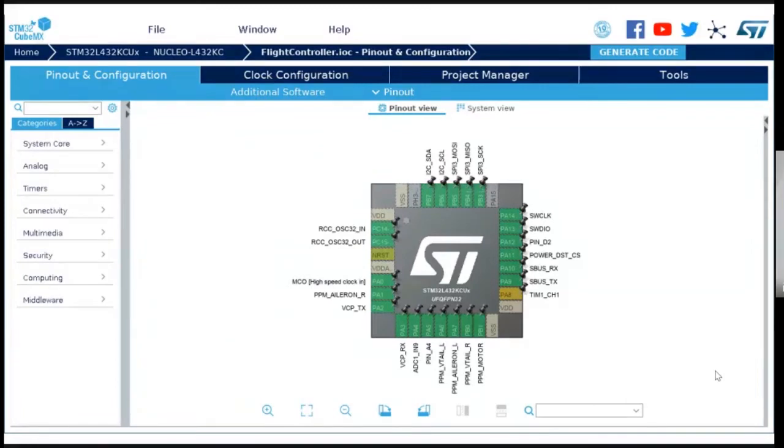That means we can write code just like we do in the Arduino IDE. We have to write only the working part of the code, not initialize the internal features or registers, so the code will be very simple. In STM32 applications, we are using this type of code generation technique. First, we generate the code from STM Cube. Any change we make in STM Cube will be updated in our code in parallel. After generating this code, we can write simple algorithms in our program, and it is a well-structured code generated from STM Cube.